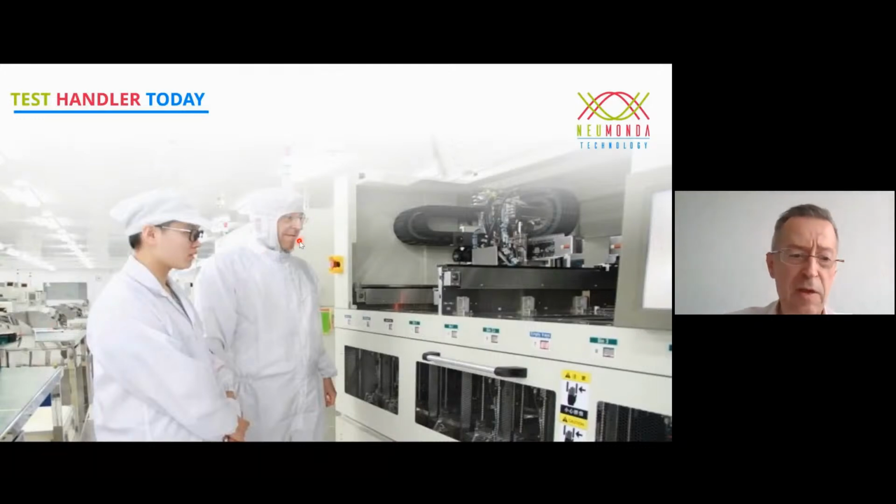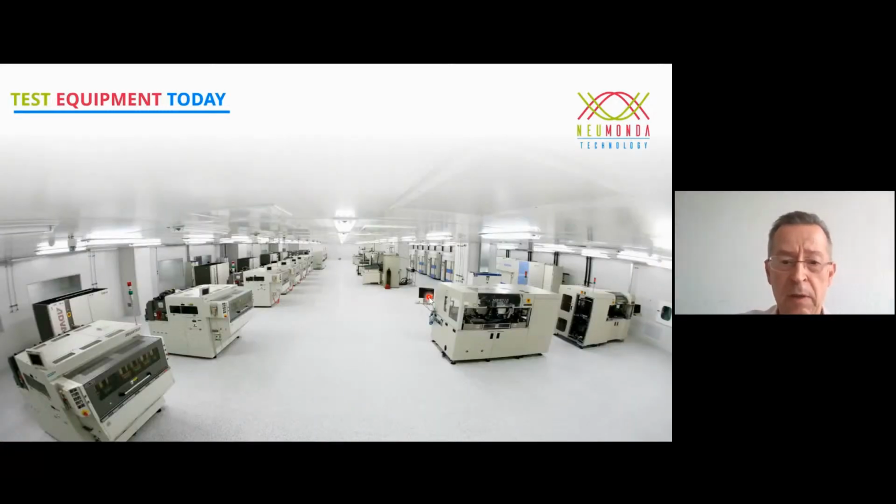So this long nose here is me being in a conventional backend. That's typically how a backend looks. This is a handler where you stock your DRAM, and then the handler is simply transferring the memory component, DRAM, or for other volume testing you have similar equipment, onto the test head, provides the right temperature, and does the testing of the circuits.